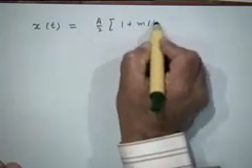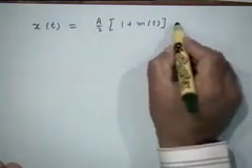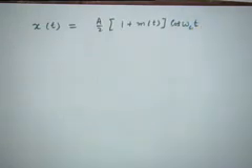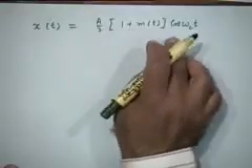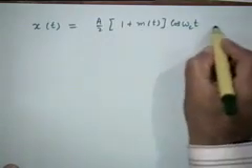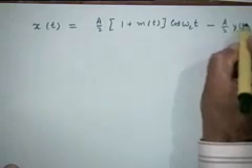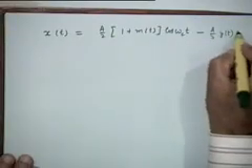Once again, this carrier part which I have introduced is because we want to be able to do envelope detection in the same manner that we did for SSB, right? So this part will be the same as we have for the SSB, plus of course there is a carrier that I am introducing here, minus A/2 into some low pass signal y(t) sine omega c t,